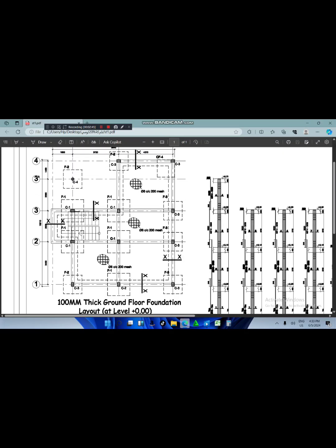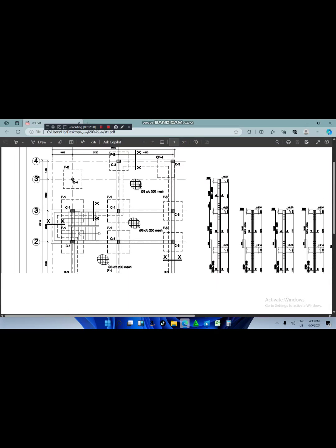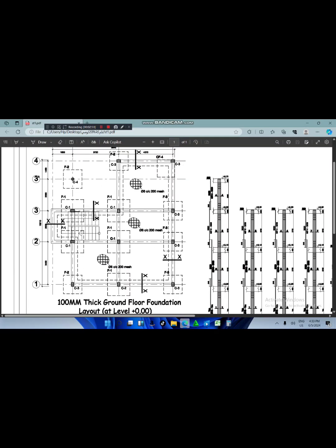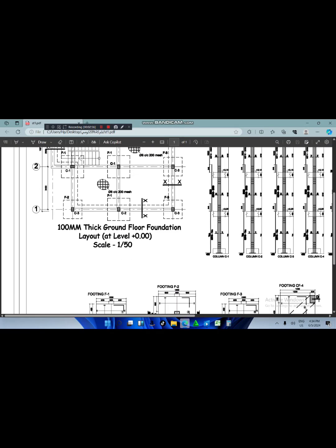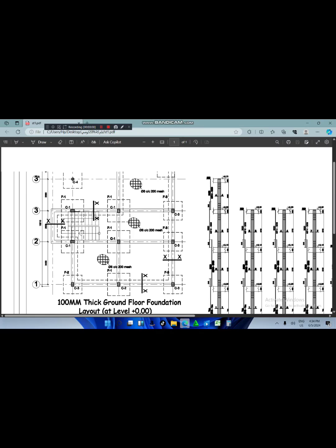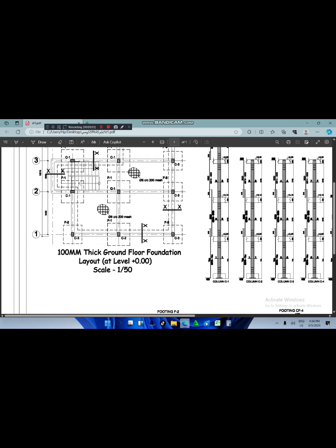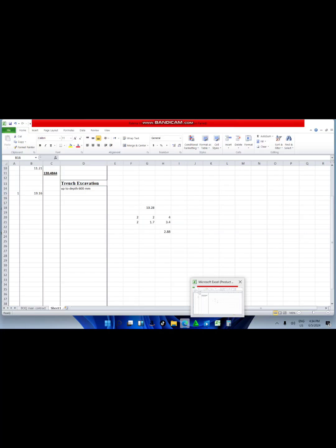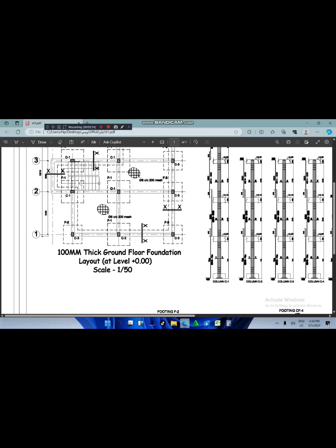I have here the sectioning. Okay, I have also here 3 columns that will be deducted from the length of the wall and flat, because I already calculated it in the pit. Do I have to calculate it in the trench excavation again? So I will take the length. The length is from here, 10.